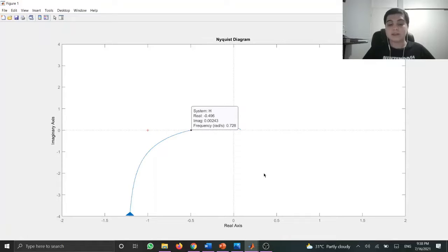A Nyquist plot is a diagram where the points plotted represent the magnitude and phase of the open loop frequency response, corresponding to a particular frequency. In order to build this kind of diagram, we need to know the functions of magnitude and phase of a system that depend on the frequency. So the point is going to depend on the phase and gain at a given frequency.